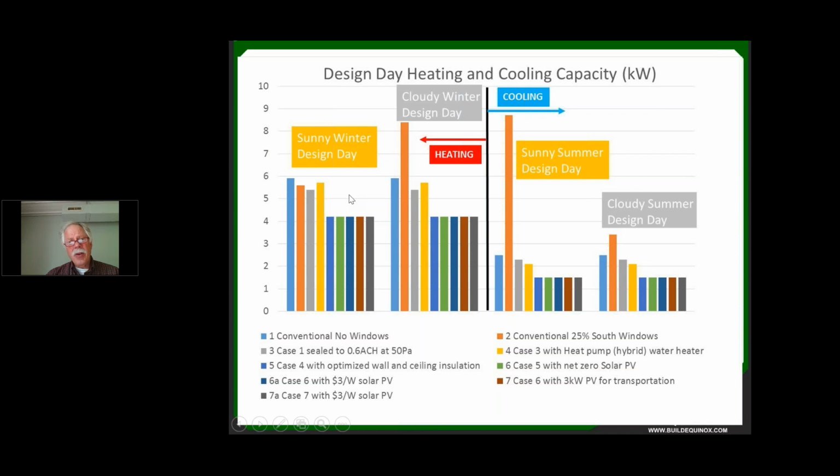When you have today's high-quality home heat pump space heating systems, cold weather heat pump space heating systems, coupled with an efficient heat pump water heater, even though this increase in heating capacity was needed to make up for the cooling effect of the heat pump water heater, this is a very, very modest increase. And in fact, you can see that this increase is much less than where our original case was with a standard water heater and conventional design.